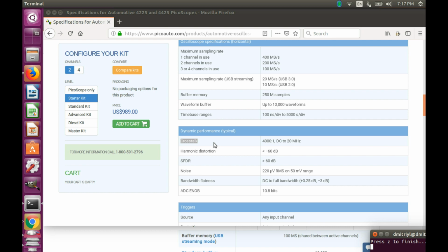And there could be two reasons for that. One is that it's actually the ignition waveform imprinting itself on the signal that you are measuring, because all the wiring is pretty much like antennas. But there could be a second reason, that inside the oscilloscope itself there is an interference from one channel to another, and that's why you see this signal.